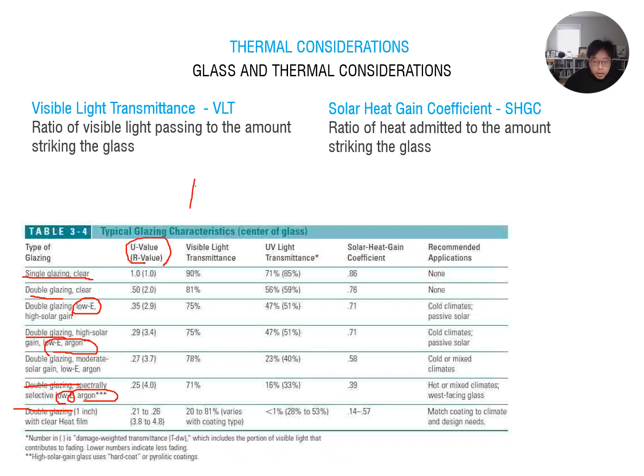You remember, R value is the resistance value; a higher R value means better thermal performance, and a lower U value means better performance. So let's look at some comparison with the single glazing system. For example, it is 1.0 U value, 1.0 R value. But when you have the double glazing system, it's hard to see, I can zoom in.